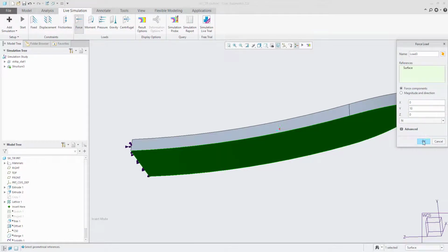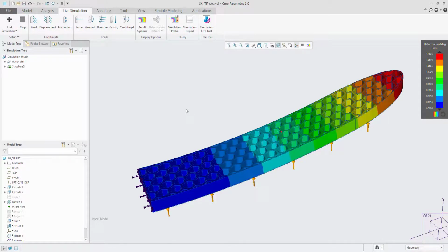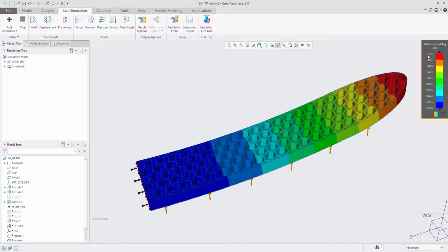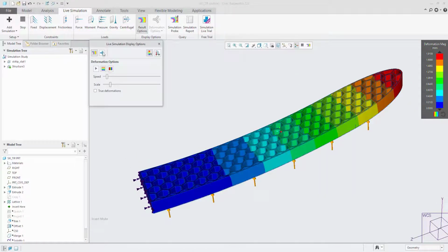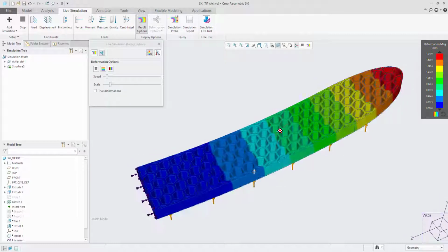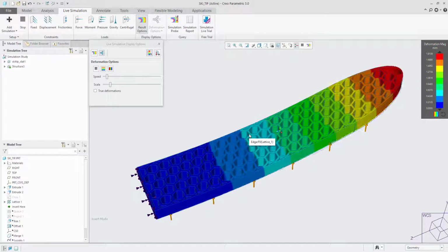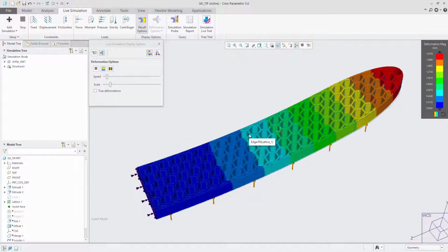and as soon as I've done that, I can start the analysis and get instant feedback about the deformation of, say, 1.9 or some kind of deformation. So let's have a look at an animation of displacement. Yeah, that looks reasonable. First thing you always want to do is make sure that the results look reasonable, because you can use a lot of your engineering intuition and design intuition to make sure that you haven't put loads in the wrong direction or constrained it in an unexpected way.